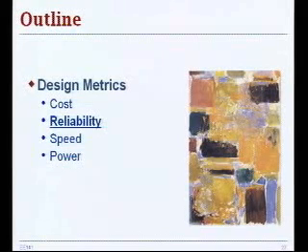You would expect your voltage levels to be at a certain value, but in reality that doesn't really happen, and there are a number of reasons why you can have deviations from your ideally desirable values, and that is attributed to noise. So you have various noise sources that can do some sort of damage to your useful signal levels, and that can eventually corrupt your signal and compromise your circuit behavior.